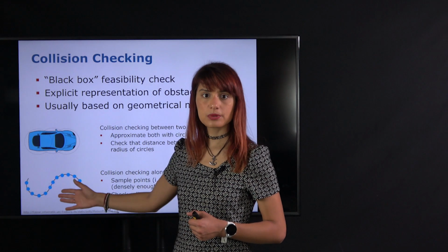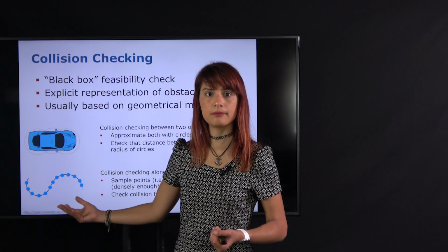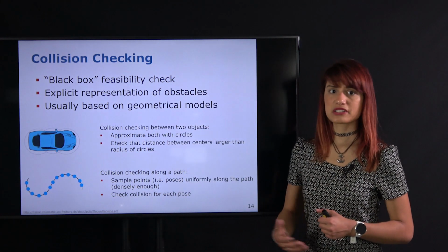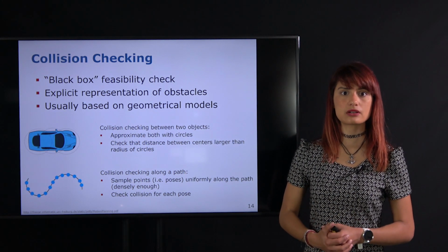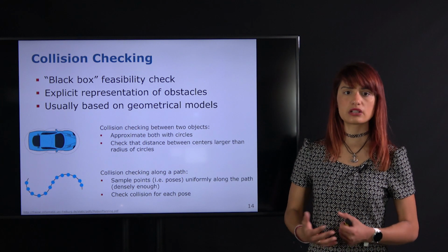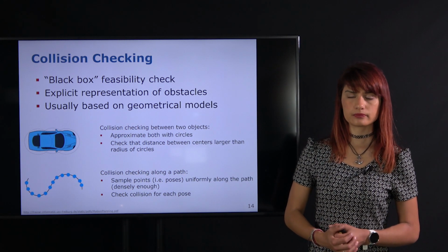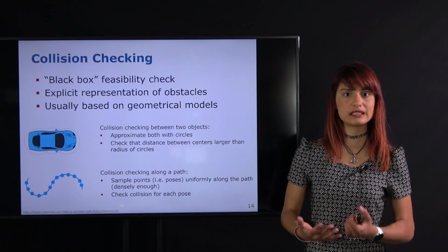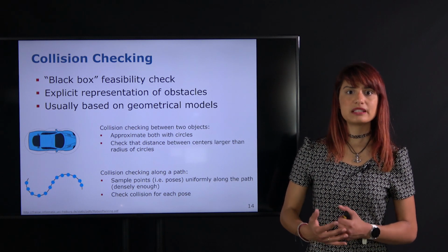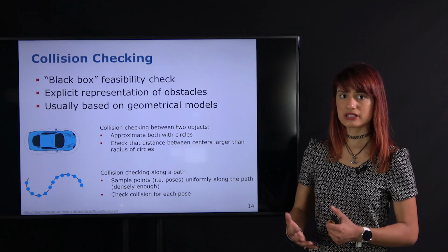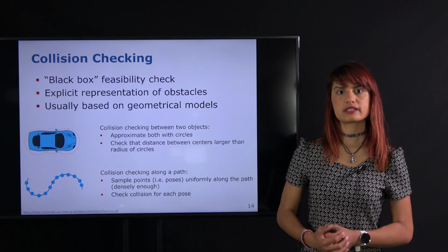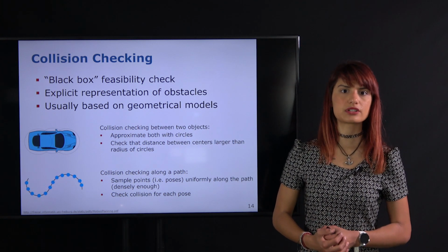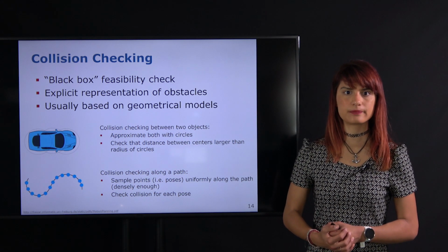And of course, it's relatively intuitive that this subsampling especially could take a lot of time. So actually 90% of the time that we invest in a sampling-based planner often comes from the collision checking step. So there are many techniques for actually speeding up the collision checking procedure in order to obtain higher computational efficiency, especially for very time-critical problems and robots.